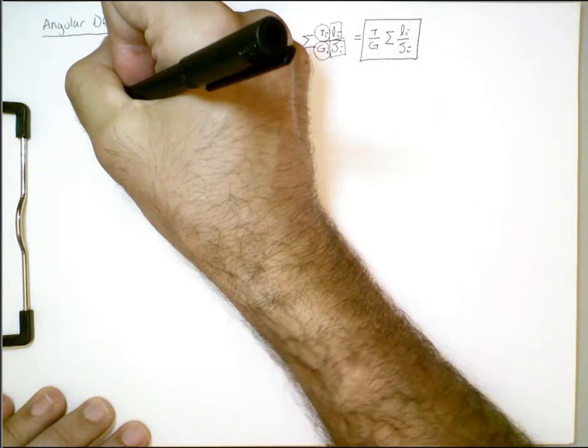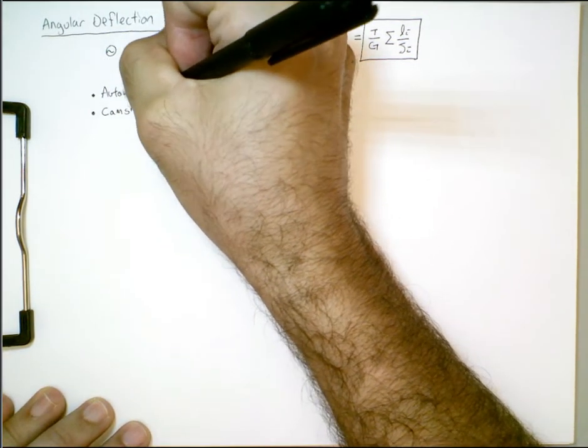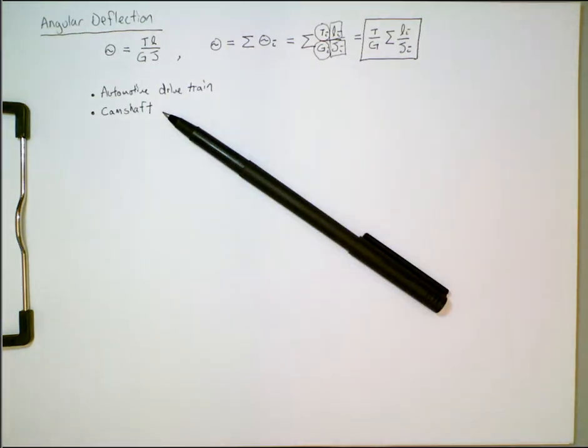Here's another example that's important from the automotive world. Earlier in class we looked at a video that showed some animations of the internal mechanisms of an automotive engine. It involved things like a crankshaft and a camshaft and push rods and timing belts. So the camshaft, its job is to open and close the valves that let the fuel-air mixture into the cylinders, and then also open the exhaust valves that let the burned combustion gases exit the cylinders. And it's really important that these valves are opened and closed in a very precise way.